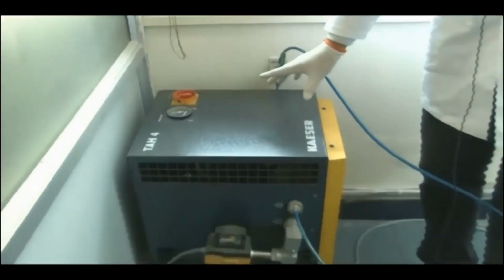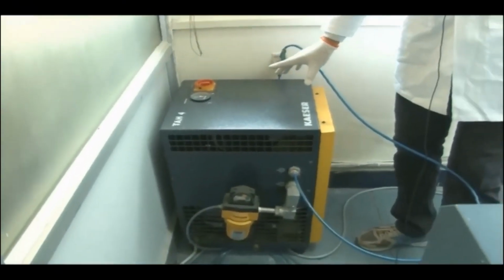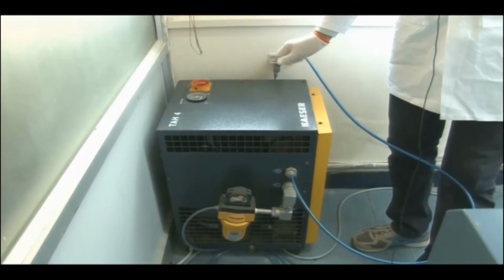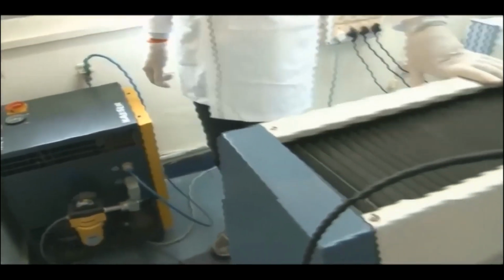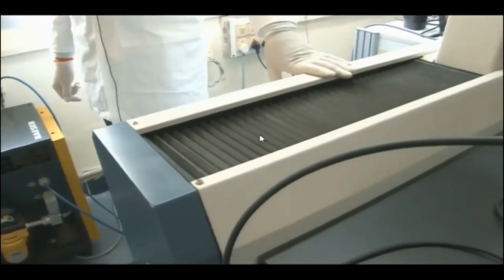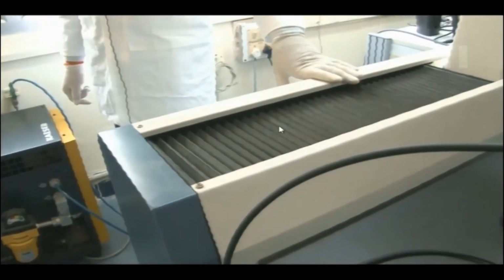It is a refrigeration type air compressor. It is 100% moisture free, so it is not going to harm the machine. The compressor that we use here has to be moisture free. We are trying to save the machine from dust and other impurities using these bellows, so that dust particles do not come in between the moving components and act as abrasives. It may deteriorate the machine in the long run. To prevent that, and also to save the machine from corrosion, this kind of refrigeration, moisture free air compressor is used.